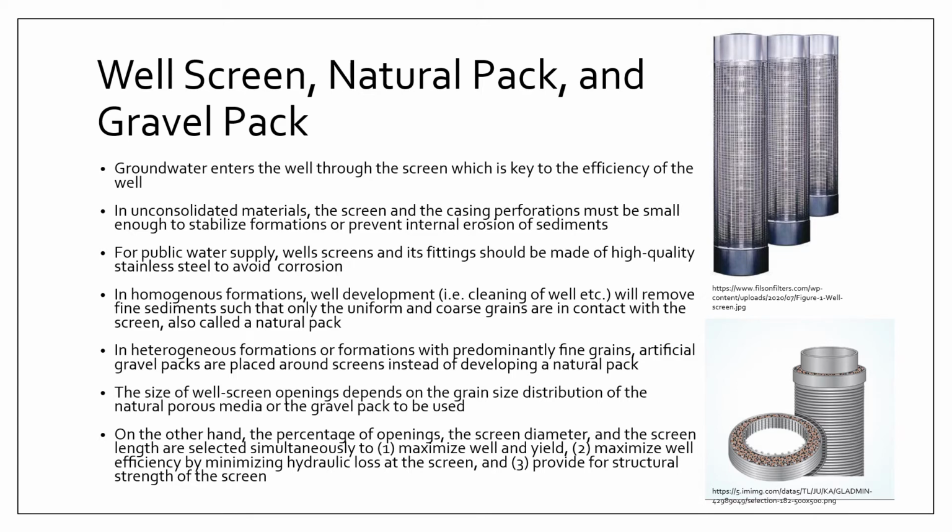Now, when we are talking about public water supply, where water quality is one of the priorities or important features, the standard material used for well screens is typically high quality stainless steel, which is highly resistant to corrosion.